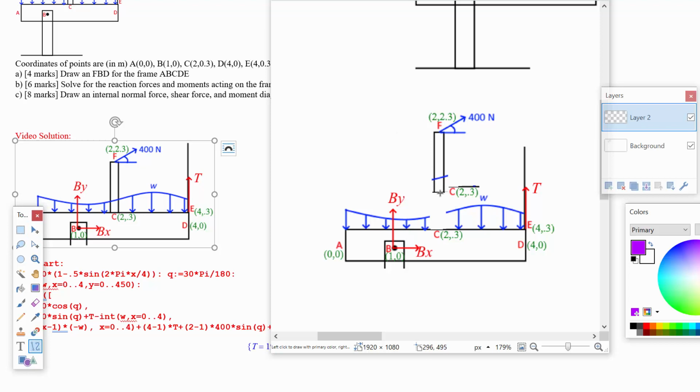So you can look at this thing and think what has to be applied at the bottom. We've got to have a force. I mean, you could just jump right in and say, well, for sure, we're going to have force the same as the forces F at a down and 30-degree angle there. But let's pretend we don't know that. Let's just do the standard way and call this CX. And another one like that, which is CY. CY, labeling them both at once there. And we're going to have another CX here as a Newton's third law action-reaction pair applied to the bottom like that. Okay, but that's not it.